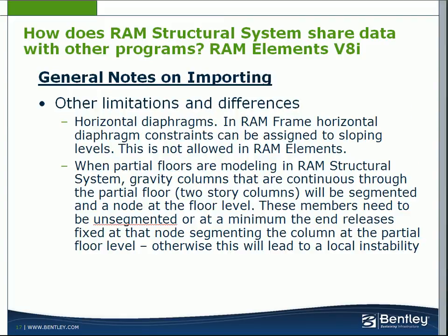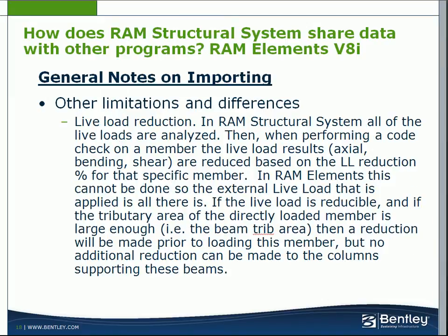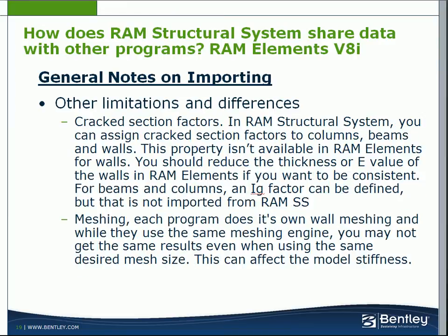Some other limitations and differences are explained here, including that live load reduction is not done automatically as it is in RAM Structural System. Crack section factors and K factors do not get imported from Structural System into RAM Elements.